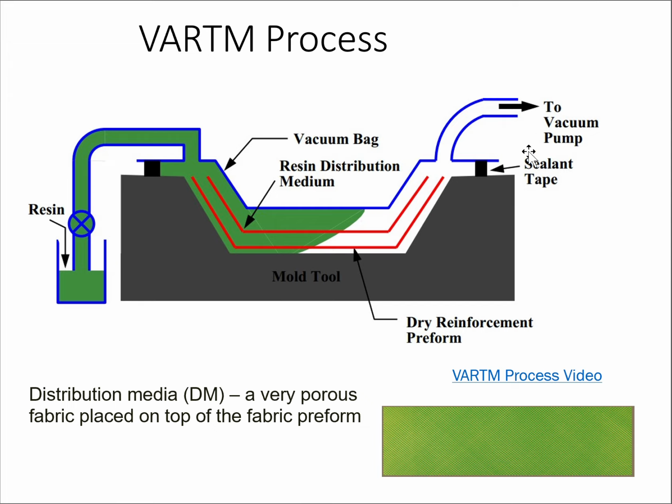You have an outlet to the vacuum pump. Right? And then you start vacuuming your sealed area, which is going to bring the resin in. Whenever the resin starts reaching the vacuum pump, your job is done, and you just have to let your composite cure. Plain simple.